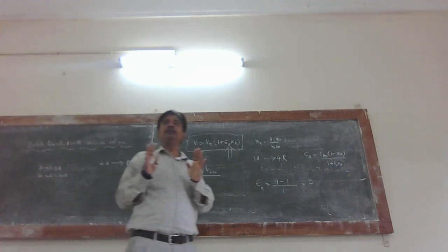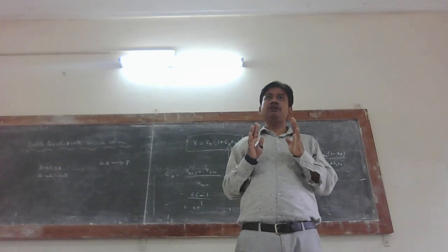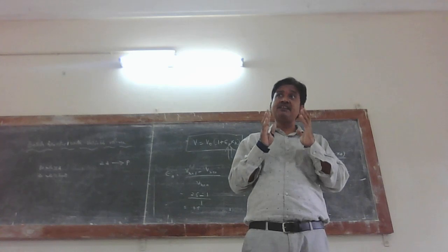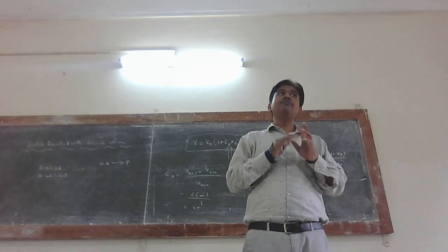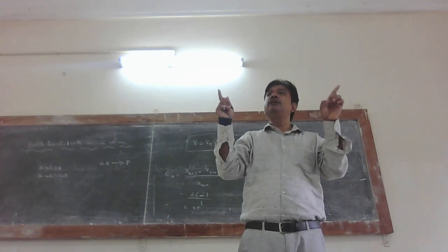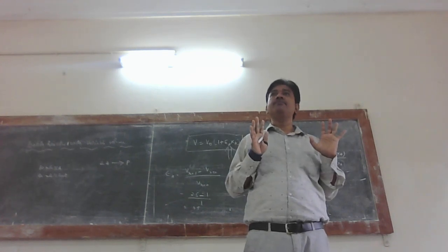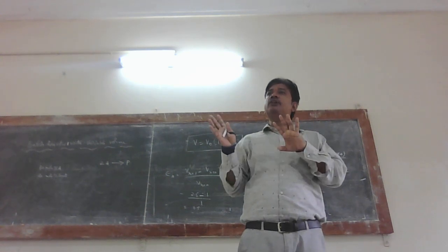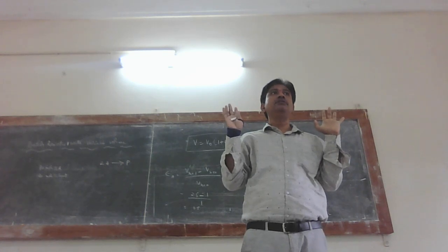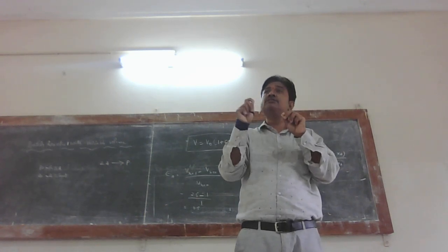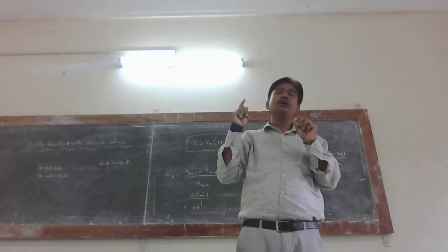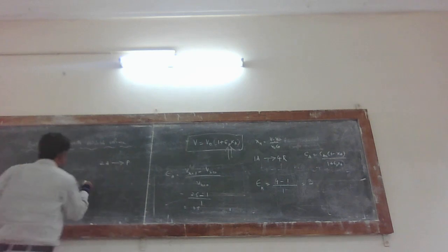First order, already he has mentioned first order, and he has also mentioned pressure is kept constant. Pressure kept constant means volume is varying, that is the only indication. So it is a variable volume problem. Whenever a variable volume problem comes into picture, epsilon A should come to our mind, because epsilon A represents the fractional change in the volume. Now we need to calculate epsilon A.